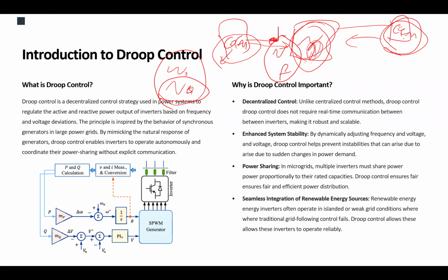So grid following needs a transition period, from zero to when they could reliably connect to the grid, from the initial value to the optimum value of their control system. That's not the case in grid forming. They are set before they start working, so they connect and they start working. Are we good?